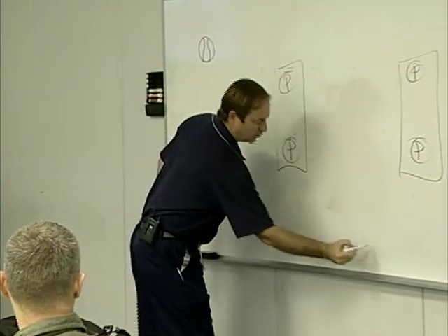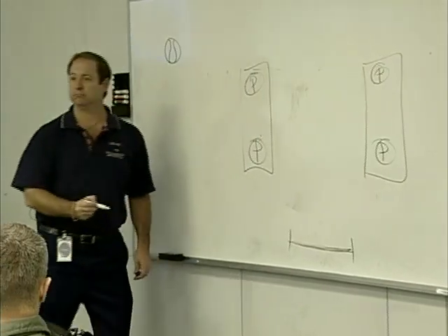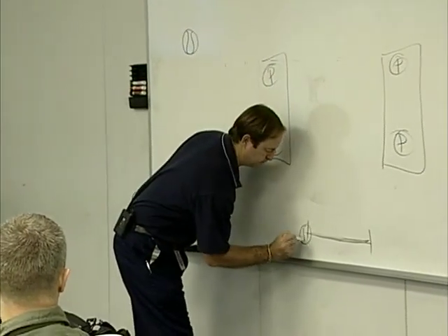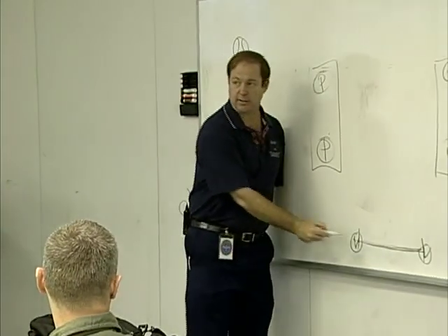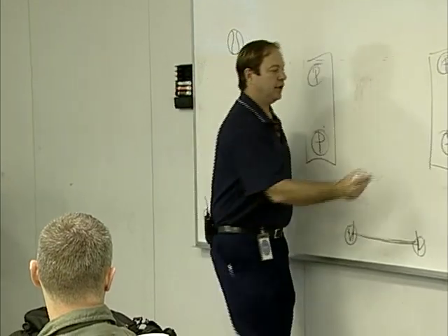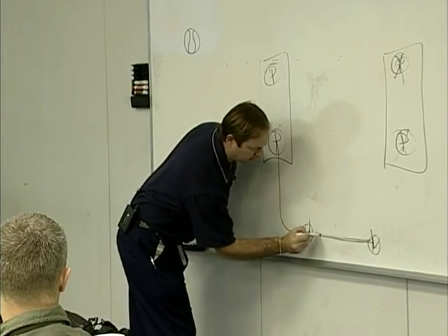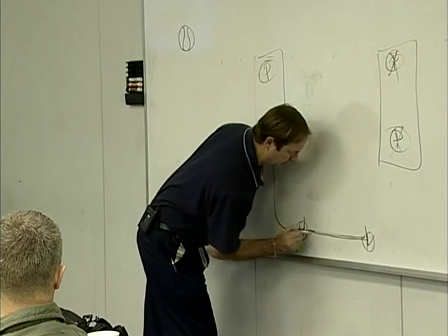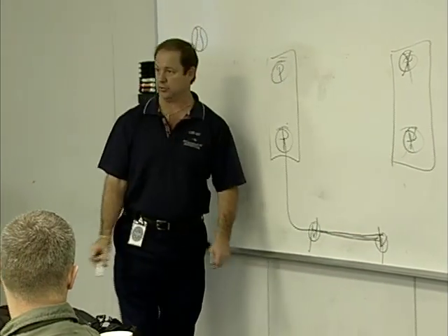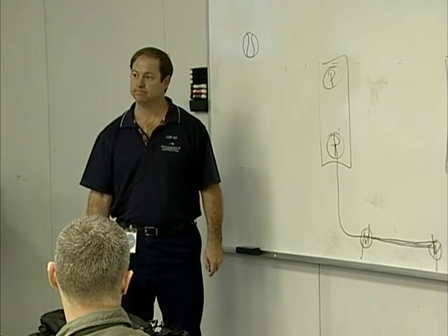Okay? Back here we have our crossover line. Valve here, valve there. Good? Now, when I open the crossfeed, both these valves are going to be open simultaneously. Good? If these pumps aren't working, that pressurized fuel is going to go through here, and it's going to feed this engine still, and now that pressurized fuel is going to feed this engine. But to stop the fuel up there, I have to pull the fire handle.